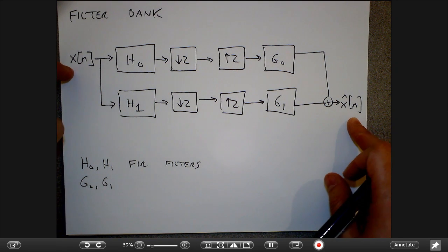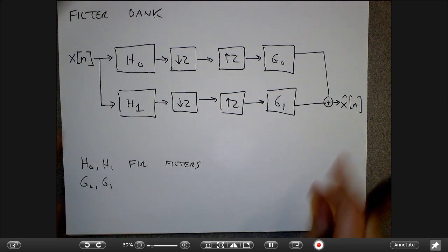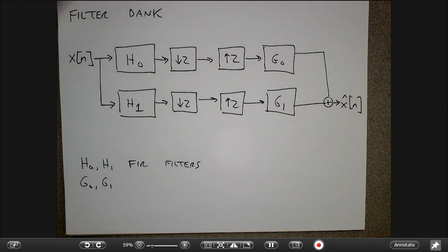That means that I have not really distorted the signal at all. I mean, in practice, if these are causal FIR filters, I can't actually get exactly the same input because if everything is causal, the most I can get is a delayed version of the original signal, right?